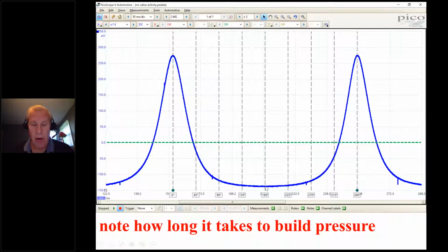This is bottom dead center. Now, if you think of the conventional compression stroke, the way that most of us learned the compression stroke, it started at bottom dead center and it ended at top dead center. And that's always been a fairly convenient way to discuss it. But take a close look here. I'm going to start at bottom dead center. Now I'm going to call that 0, even though it's 180 for my reference, but that's just my starting point. So 0, 45, 90, 135. That crank has rotated 135 degrees out of a possible 180, and we're still in a vacuum.